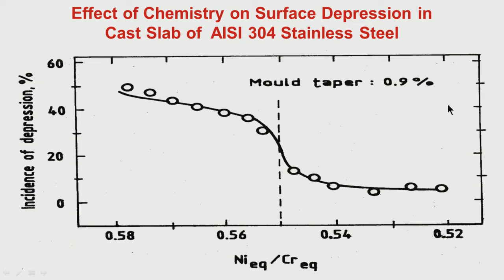Now as I have mentioned, because of solidification there will be some shrinkage. So at the top of the mold solidification has not yet started. So the gap between the two broad faces, that means two plates which constitute broad face, the distance is something say x.